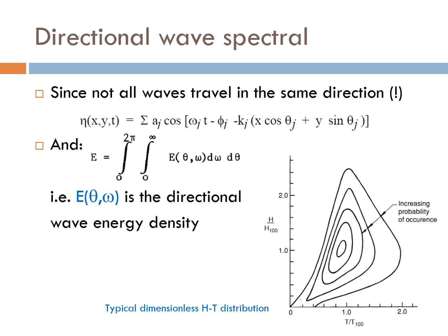In our previous discussion, we focused on analysis of the wave height and the wave period, which basically uses the same approach. We are also going to highlight here that there's one more component of information that's very important, which is the direction of the wave. So in most coastal applications, we will also be interested to know what is the predominant direction of the wave. Where is the wave coming from? In order to do that, we will have to analyze the directional wave spectra so that we are able to identify which direction the wave energy density is the highest.